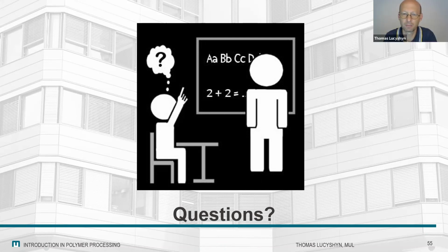Normally not. So normally you put the additives into the bulk material and then it's extruded. So it's almost a homogeneous distribution of these additives everywhere in the material. So it's not like a coating. It can happen though that during processing or also in use they diffuse to the surface and then form some layers which you don't want, or which you want to have some protective effect. So it depends on your application, but typically they're distributed all over the material in the extrusion process.